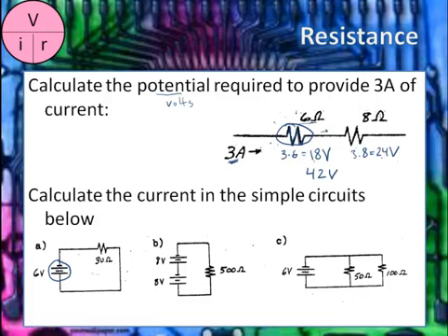So this circuit doesn't really serve a good purpose unless it's a heater. Suppose a toaster would have something like this on a much higher voltage. But anyway, what sort of current is running through this resistor and through the whole system? So if I've got 6 volts that run through this, and I'm looking for current, current is, if you cover up the I, you get V over R. And so that is 6 volts divided by 30 ohms, which works out to 0.2 amps.